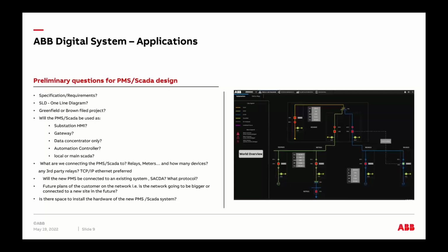Again, going back to my greenfield and brownfield topic. Is it greenfield or brownfield? Again, you need to know that. Because once you implement your HMI, maybe you're going to keep some of the old protocols or maybe another network they don't want you to touch. However, they want you to pull data from that network in parallel with, for example, your 61850 brand new network that you built for them.